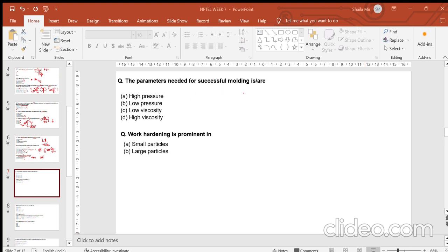That is the charging material, and it is only 30 to 40% of the capacity of the mill, because you need free space inside the mill for the powders to follow a certain trajectory, so that there will be milling or de-agglomeration, whichever you want. So this is one of the important factors.